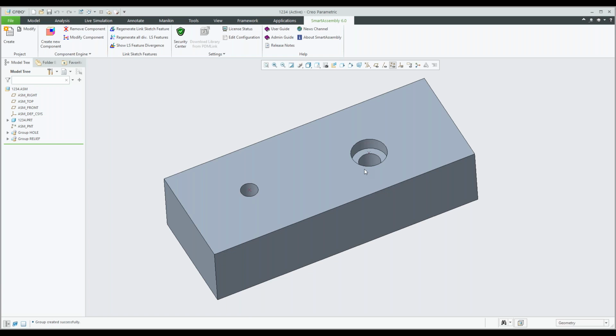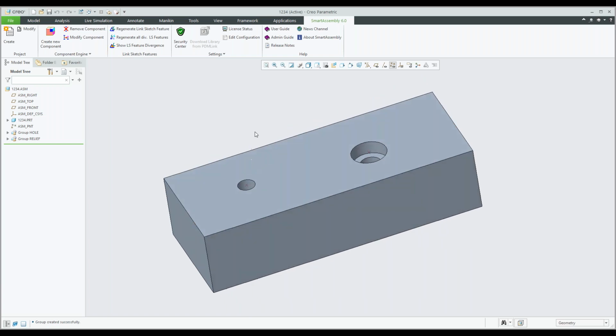Determine your references that you want to use, because my point was already here. But if you're going to use that, you need to go and create the points first, and then you can run the smart assembly application. So just think about what references you'll be using. If you're going to use user-defined features, think a little bit about how you would name them and what parameters you need to vary. So yeah, I think that's the major points that I wanted to show there.